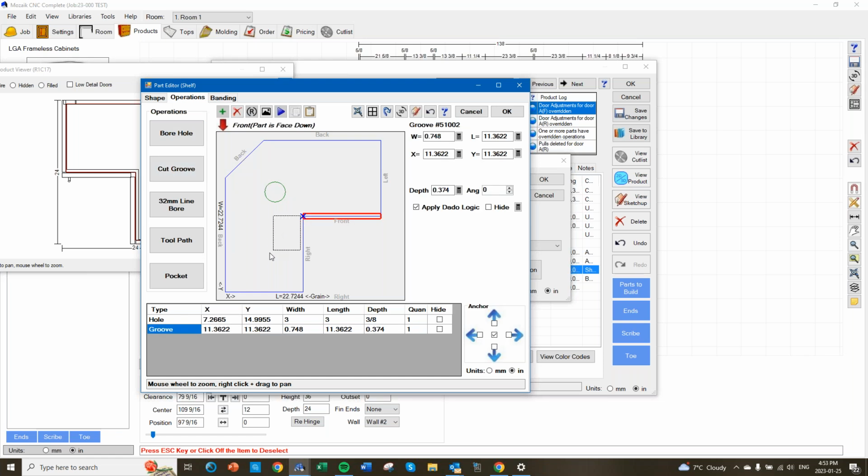For the first, we'll take this guy. We're going to rotate it 90 degrees. How wide do you make that groove right against the back edge? 7/8. Okay, so 7/8 wide. So what we'll do is we'll make it 1 inch wide, and then we're going to put that in at 5.25 inches on the X. So it's going to cut in 7/8 this way, and 1/8 of an inch off, right? So 3/8 of an inch in, right? 1 inch, half inch, yeah, 0.375.